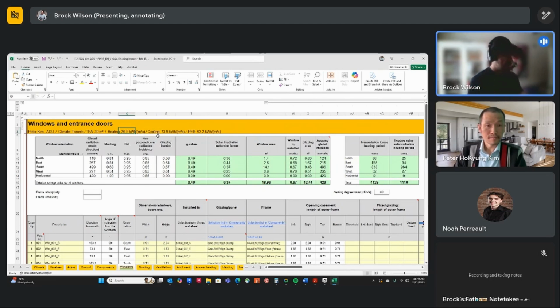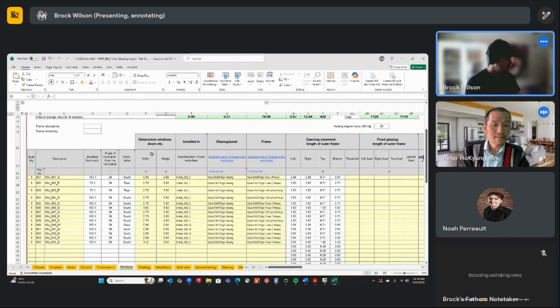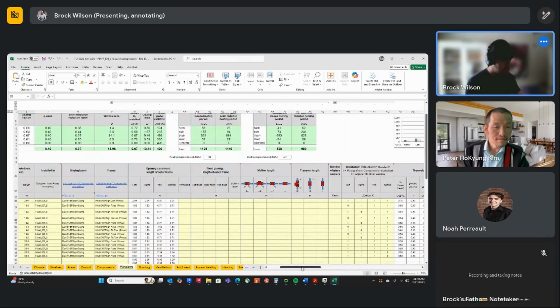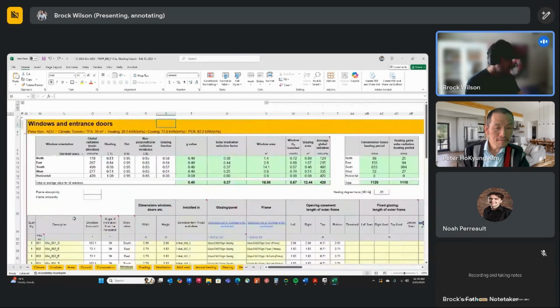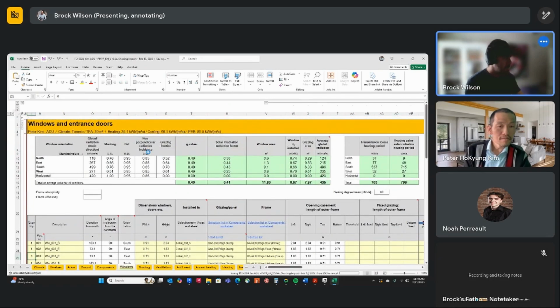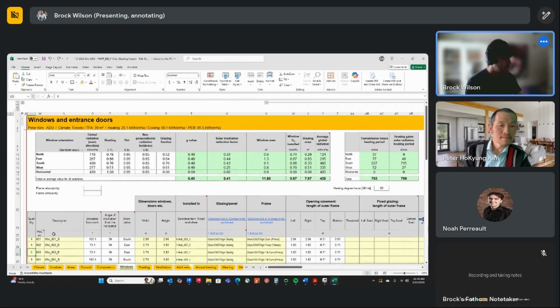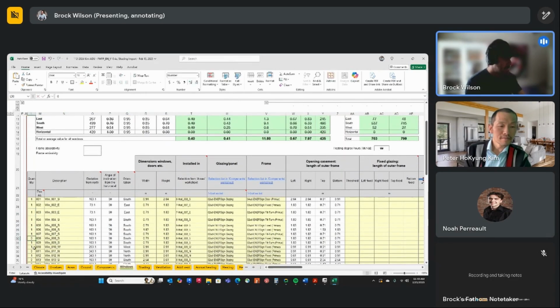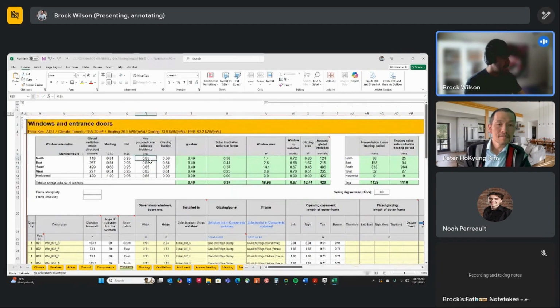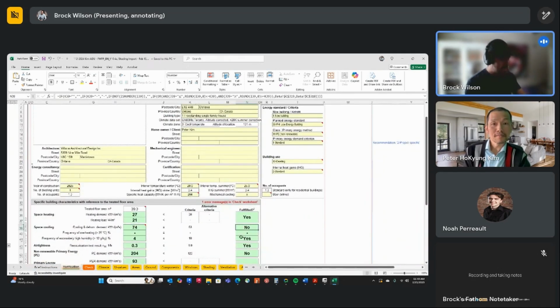So there is some impact, but the other impact that we were cautious about is your cooling load. Because even though the overhang does provide some shading, we want to ensure the cooling. So I'm just going to jump back to see. There's our cooling load at 60 right now, and then adding those windows back in, we are at 73 or 74 kilowatts. So it adds 14 kilowatts of cooling load. In that case, I don't believe our cooling demand is now met, for example.